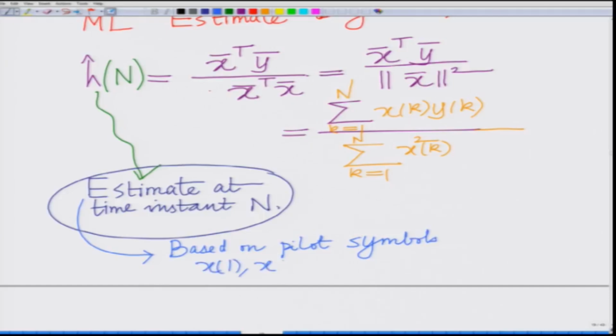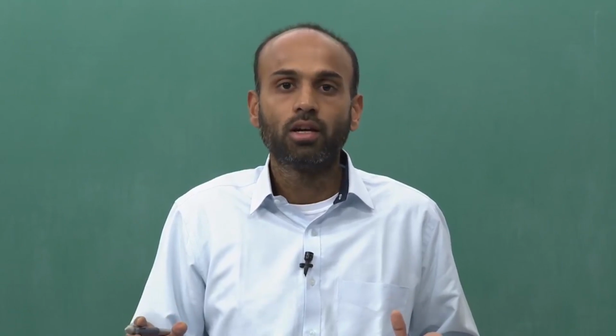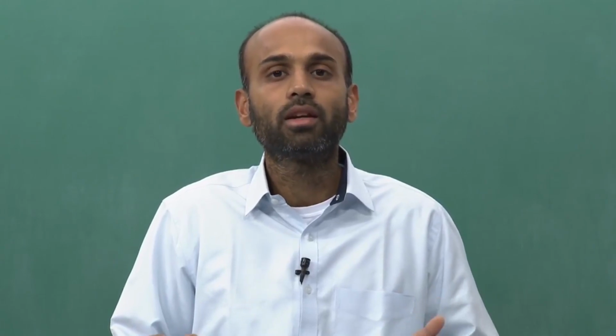This is the estimate at time instant n, okay, and this is computed based on pilot symbols x1, x2 up to xn transmitted up to time instant n. Okay, so, what we are saying is this estimation in the sequential estimation scenario is a continuous process. At each time instant we are going to update the estimate. Basically, as the pilot symbols are arriving, as the pilot outputs are arriving, we are going to continuously keep updating our estimates. Hence, naturally there is not one estimate, but there is an estimate for each time instant, and this